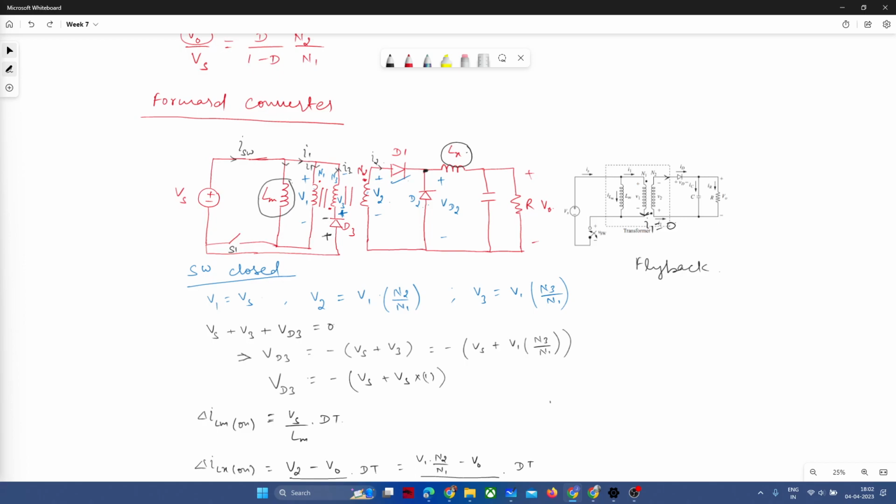Yes, sir. Great. So in the forward converter, we were utilizing a three-turns transformer, or three-winding transformer, let us say. And from this figure, we can say that the magnetizing inductance is working to supply enough current to the secondary side. It is basically helping in switching, because we cannot have DC in inductors or transformers, which basically operate with alternating currents. But here in isolated DC-DC converters we are utilizing switches to avoid constant current in the transformer windings. Otherwise our transformers would get saturated and after a certain time would be damaged. So the magnetizing inductance helps avoid those conditions.